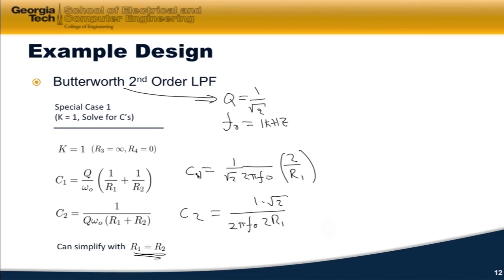Now, knowing that it's harder to find capacitor values because they have 20% tolerances than it is resistor values, the way I solved for C1 and C2 was to look at the available resistors that I had in the resistor bins in the laboratory and choose different values of R1 until C1 and C2 were close to values of capacitors that I had available to me.